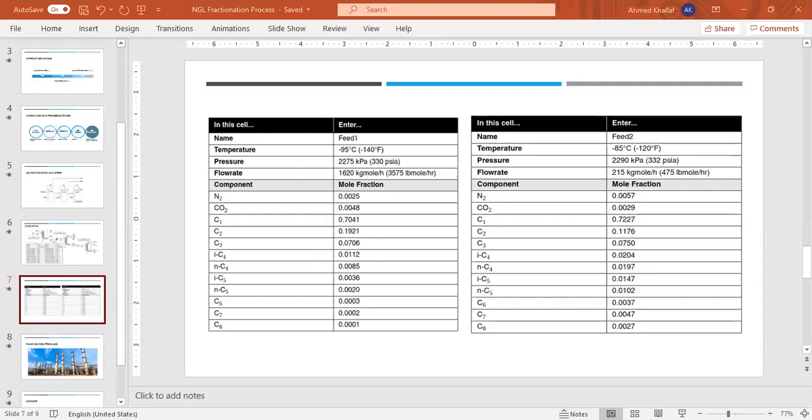The data I will enter in this program, I will share with you after the end of the session, inshallah. As you know, at the distillation column, we shall introduce feed streams and energy streams. We shall add an energy stream and name it EX duty, with a heat flow of 2.1E6.